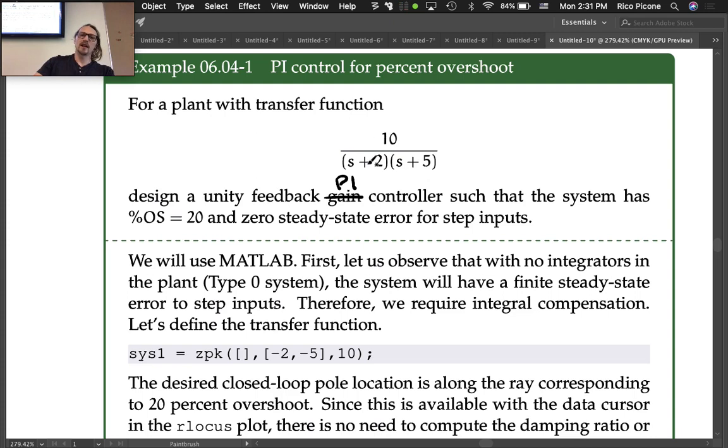And another thing to notice is that, with the gain being 0, we start off at the closed loop poles for our root locus. So we start off at 2 stable locations in the left half plane, -2 and -5. Yeah? So for the second order approximation, it was that you had, was it a 0 or a pole 3 times to the left of the 2? Either, actually. So that's another rule of thumb in terms of determining if your second order approximation is accurate or not. And we're putting a pole on the origin.